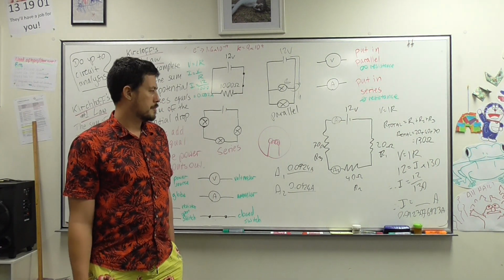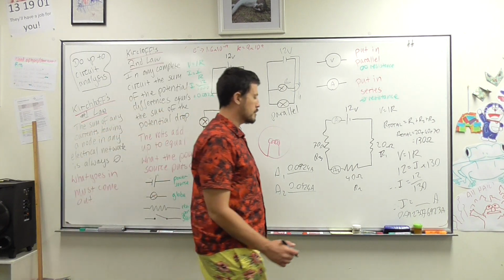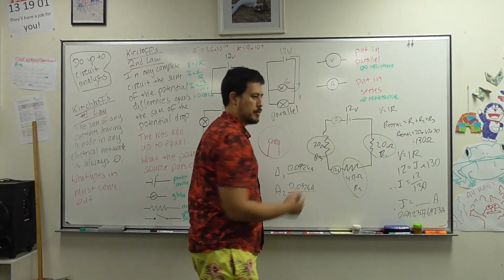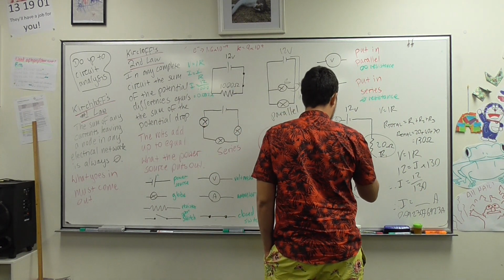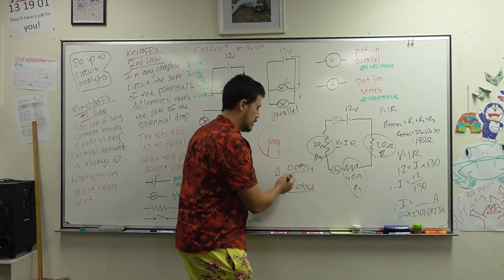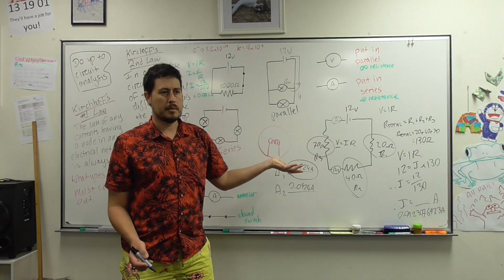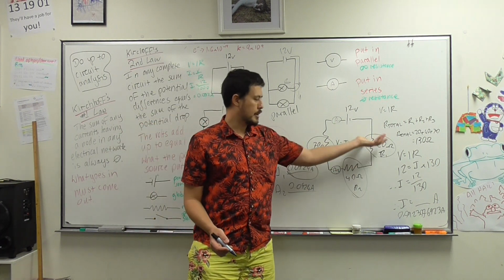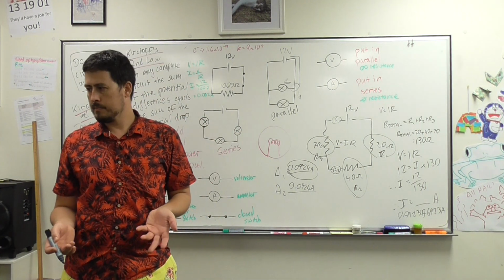But how many volts are going to get dropped across each resistor? Well, it's all going to be different. So you apply Ohm's law to each of these situations independently. The same current is going through all three, and you've got a resistance for all three. So V is equal to IR. To work out the volts for that one, and that one, there's your I. Use the R that you've been given and you can work out the V. And at the end, if it's all correct, you'll be able to add up the volts across there, there, and there, and you will get yourself a completed answer.